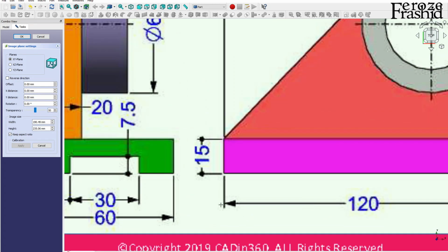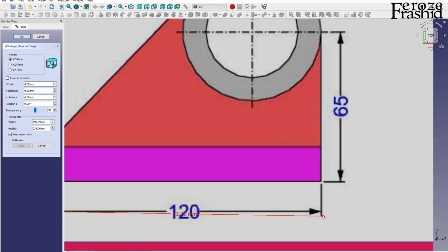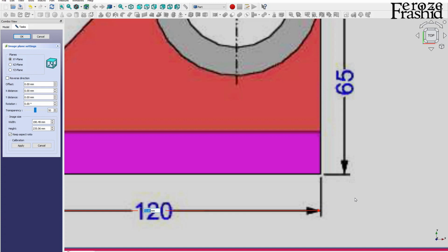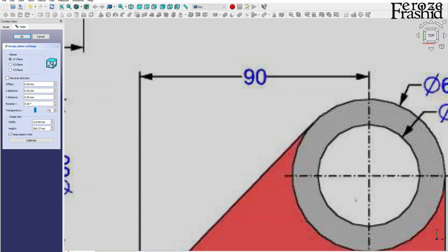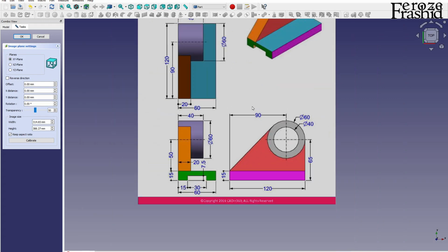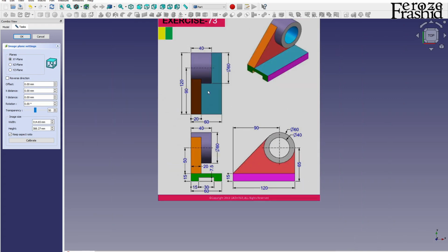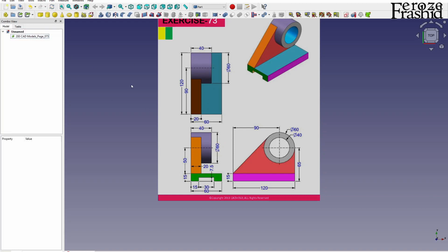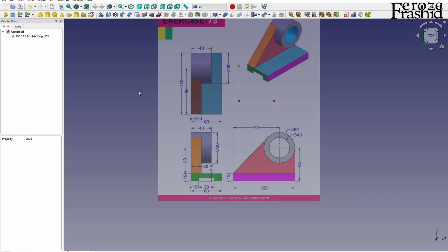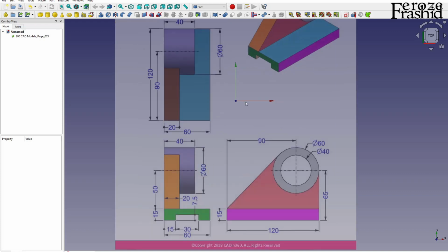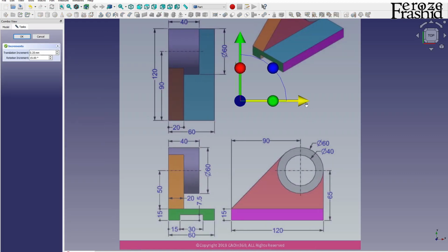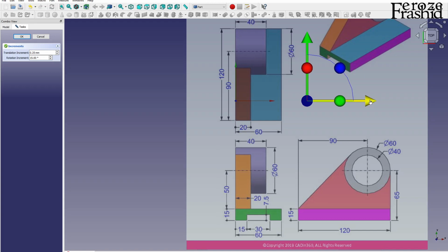I want to take the longest dimension as 20 and keep it on the XY plane. Let's start with the XY plane, right? And let's go ahead and bring our axis cross back with the AC keyboard shortcut and then relocate the image to one of its corners.